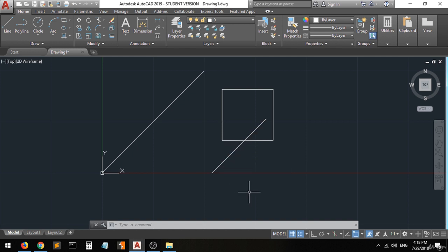Now as you can see, using the at sign will do it relative to the start point, okay? But when you don't use the at sign, it will be calculated from the origin. Be careful. So, if you do this, select the line and then specify the first point, not picking any point from here.